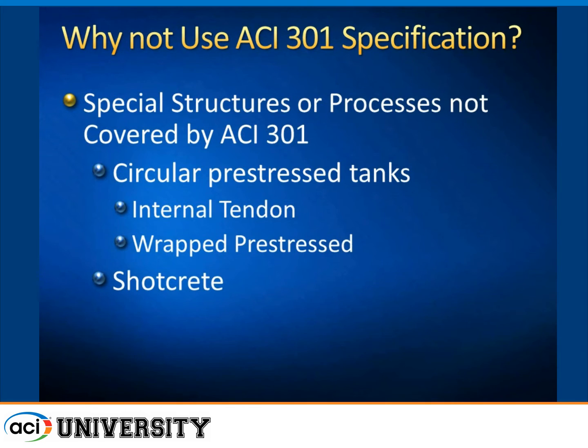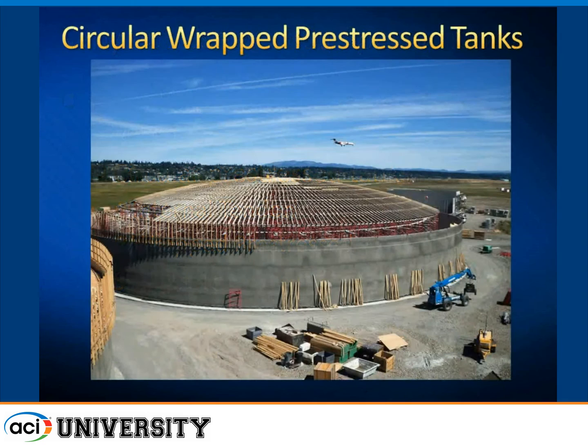318 doesn't directly deal with Shotcrete. We have a lot of structures that do use Shotcrete. Now, 318 ultimately, hopefully within the next 3 to 6 years, will acknowledge that Shotcrete is a viable material. We were a little bit ahead of the curve and put things in our code, and we also have in our specification, we deal with Shotcrete. So here's an example, a circular tank, large diameter. This has a dome roof. So we also deal with shells.